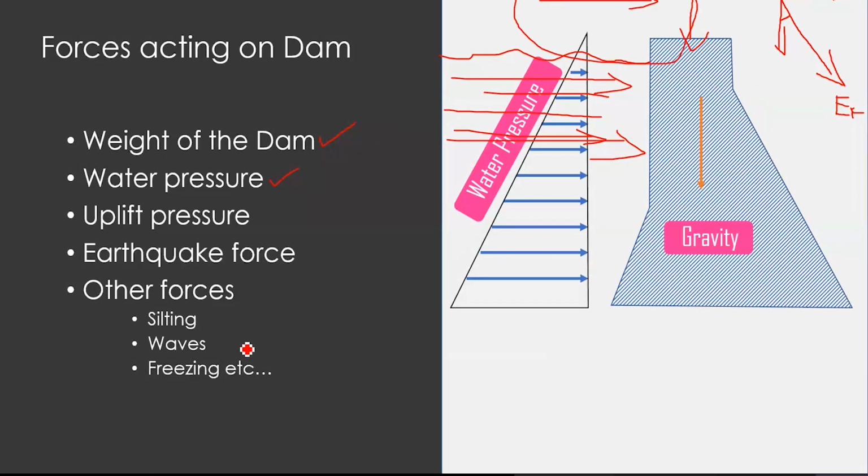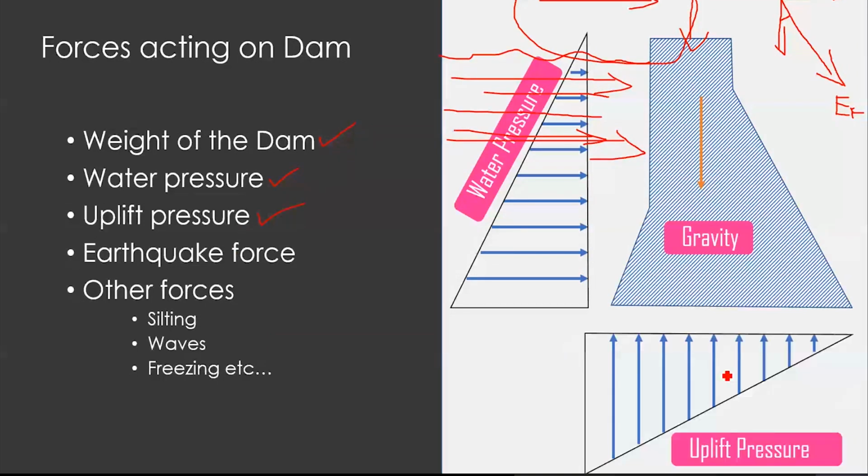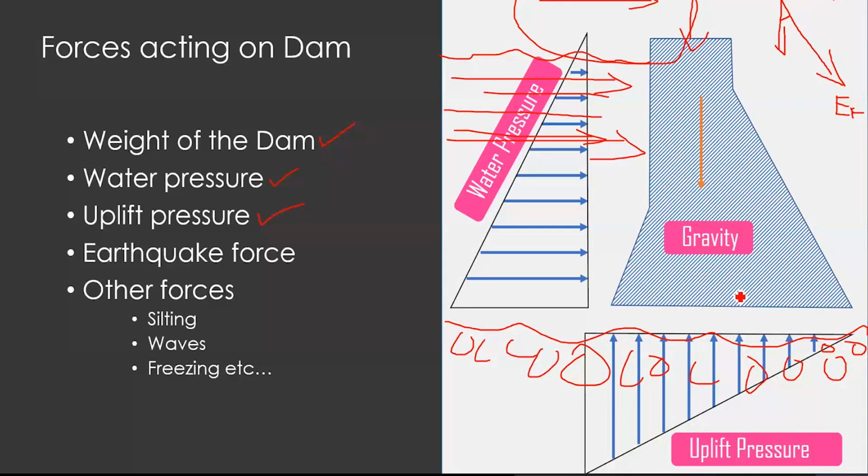Other than that, there are a few more forces which are going to act on this. This is the uplift pressure. The water which is present in the pores of the rock below the foundation will give pore water pressures, and these pore water pressures will convert to an uplift pressure in the case of the construction of a dam. Other than that, there are a few more different forces which should be taken into consideration.